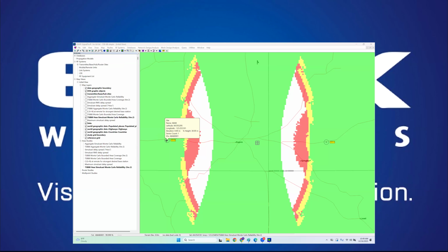So we're going to calculate the time of arrival of signal one, or the strongest signal, and then the time of arrival of the second, third, fourth signal. And each one of those potentially interfering signals gets its delay spread relative to, or the difference between, the strongest or desired signal and that potential interferer.